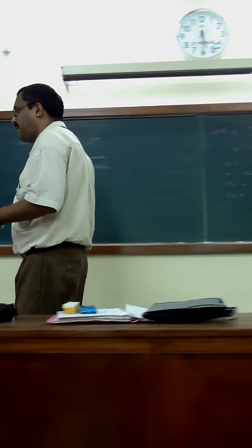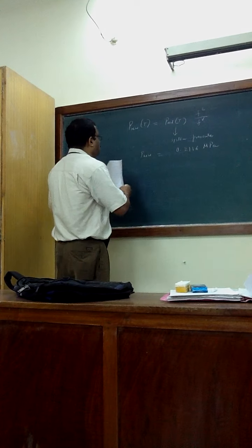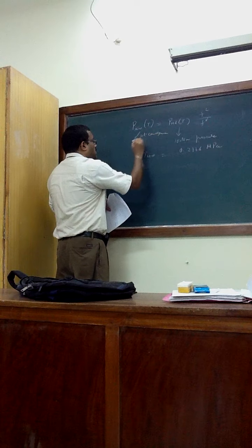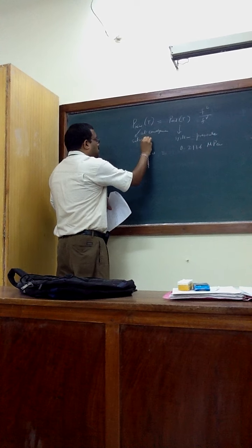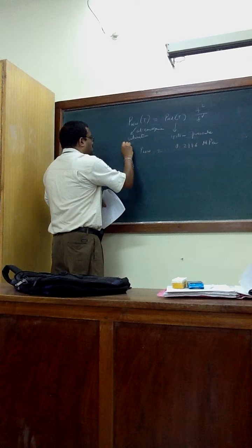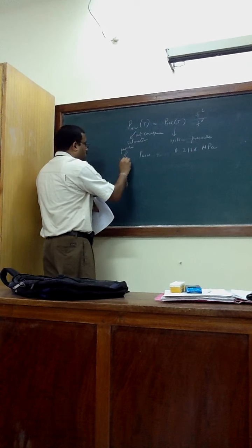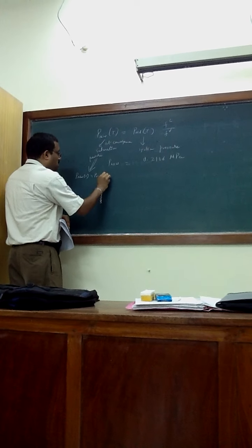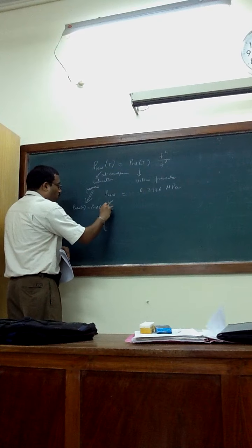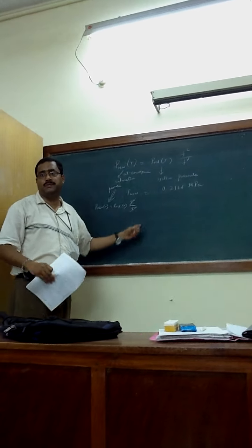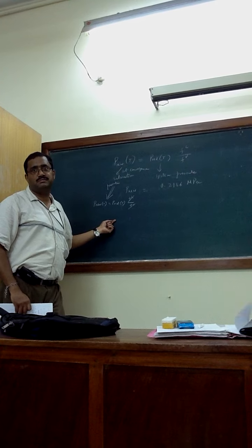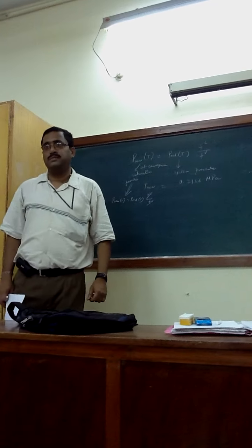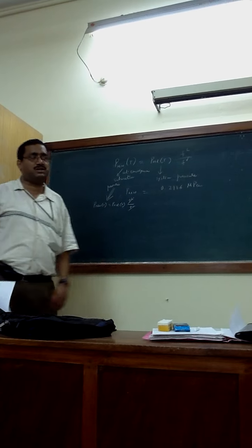At convergence, this P new will give the saturation pressure. At saturation pressure, fL and fV will be equal and cancel because they are at equilibrium. So P new and P old will be the same. If you calculate this P new and P old, you will see that they are the same because fL and fV are equal. So proceed for the same set of calculations.